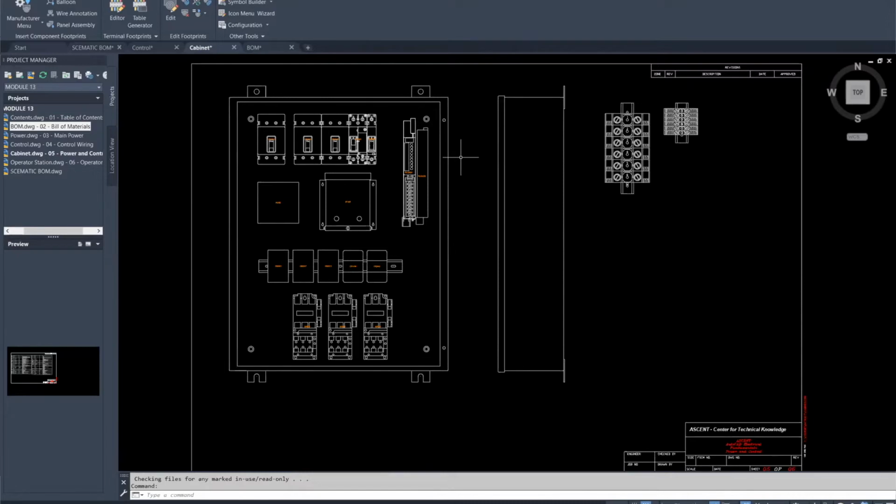So that's the beauty of AutoCAD, that I'm sharing it. It's all connected together through one database, so that if I'm changing my drawing, my schematic, I'm also changing my panel. So there's not that disconnect of: if I took this component out of my schematic, did I remember to take it out of my panel also? So that's the beauty of AutoCAD Electrical, that it's sharing the information on a database. You're not erasing it.